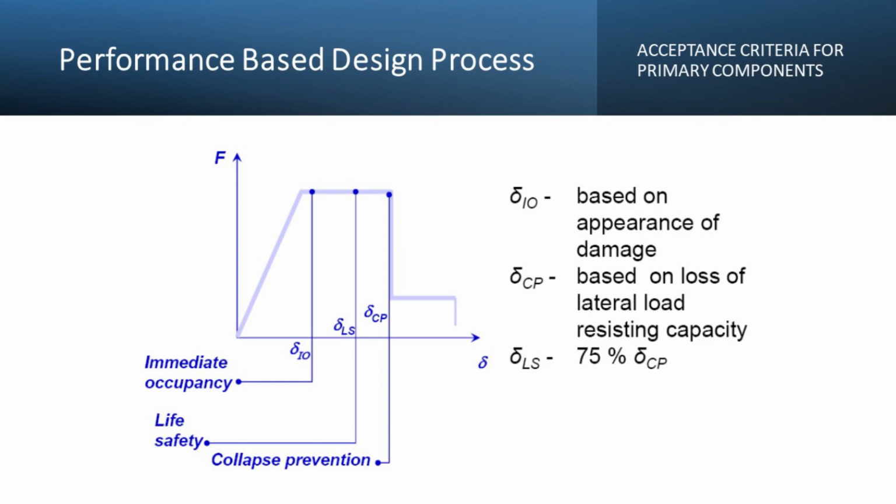So then we say, okay, this is immediate occupancy, and this curve is not of the structure performance. This curve could be of a material, could be of a hinge, could be of a member. So now we have very consistent as well as uniform application of the performance indicators coming all the way from earthquake down to the members' behavior that we determine or the calculations that we do. And these are the checks that we perform. And they all have the same sense. There's a deformation, there's a force.